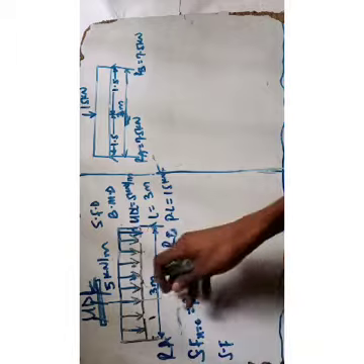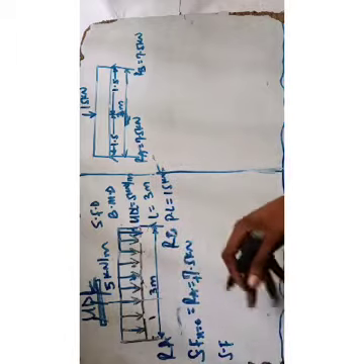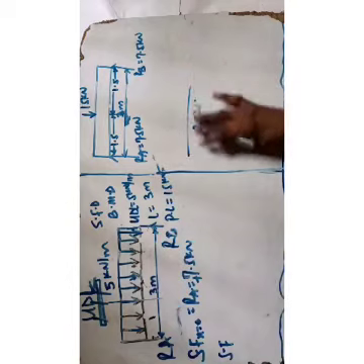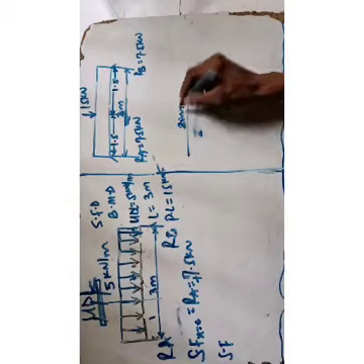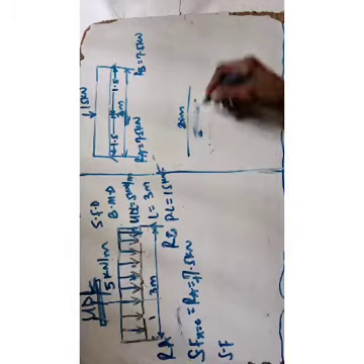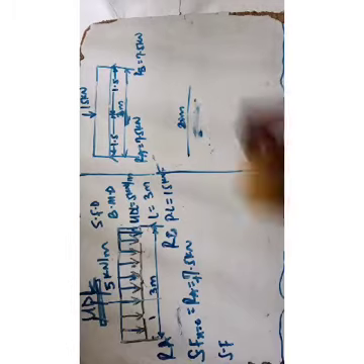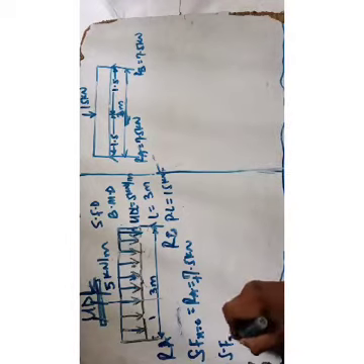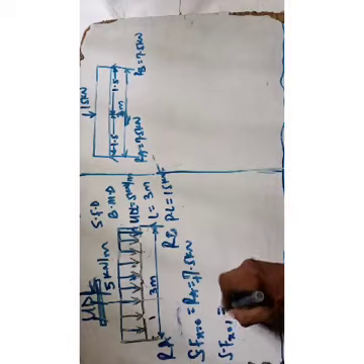So someone will say, what if it is 20 meters? You will not have to do one by one. If it's 20 meters, you will split it into, let's say, 5, 10, 15, 20 to not waste time. Or you can say 4, 8, 12. You can split it to varying lengths, but you must let it be equal. So for shear force, when x equals 1, it will now be your RA.